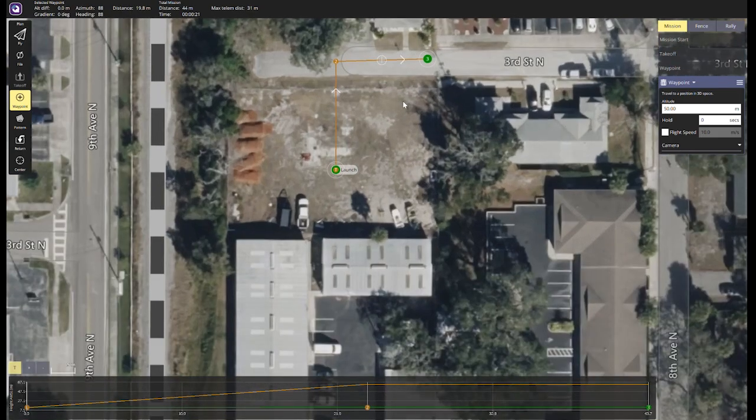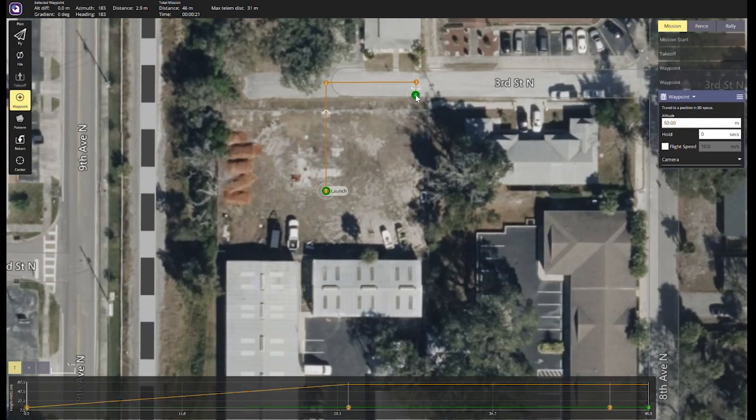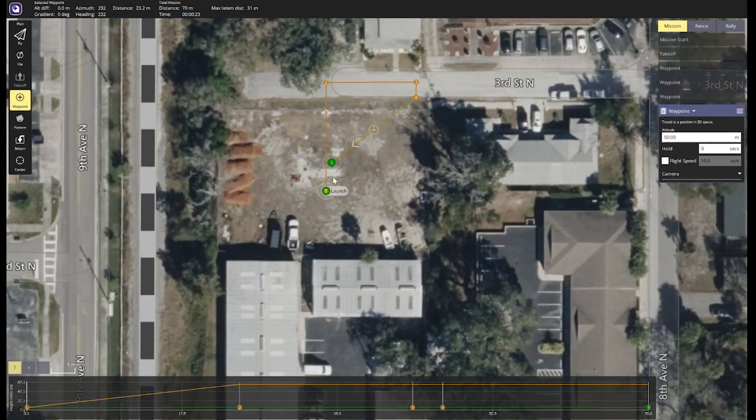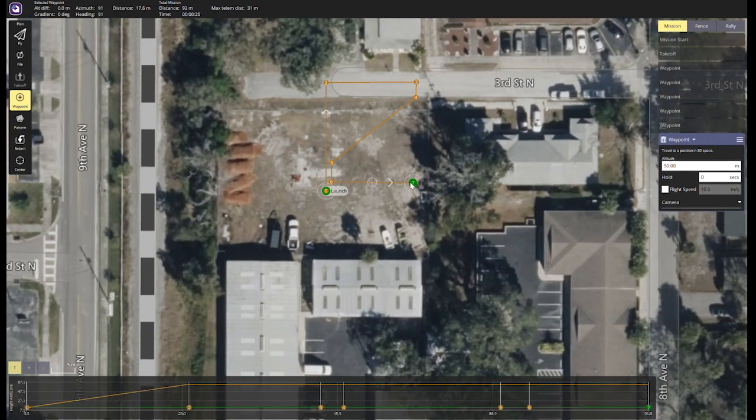Each mission will be different depending on what equipment or payload you are working with. For this example, we will be flying with a LiDAR sensor, and will require a figure 8 initialization before and after you scan your area of interest. We will create our mission accordingly. On the left side of the screen, press the Waypoint tab. Once the Waypoint tab is highlighted, you will be able to set your mission waypoints.